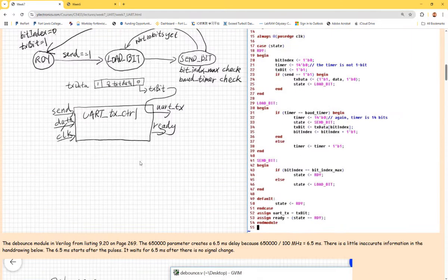Okay, so that is why the output has a UART underscore TX, and that vector is just 1 bit. It's sending out bit by bit, so eventually it's directly shorted to TX. Clock is a 100 megahertz clock. You're using that clock for the timing purposes.